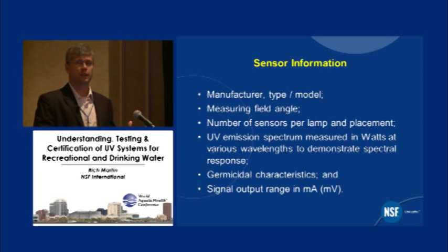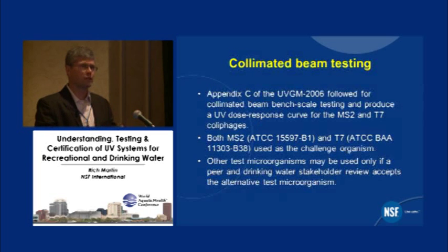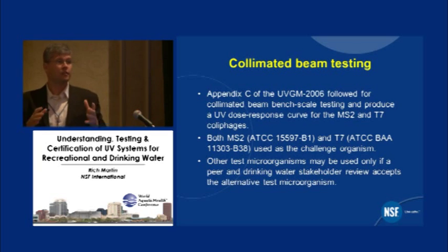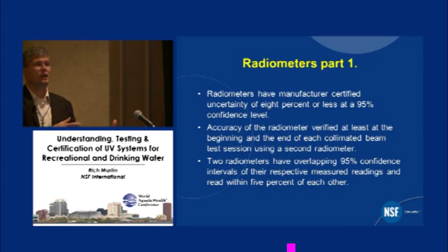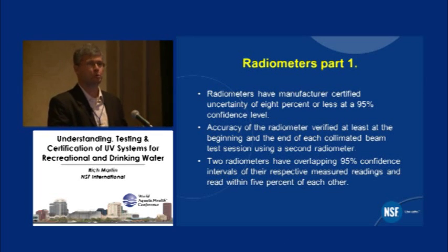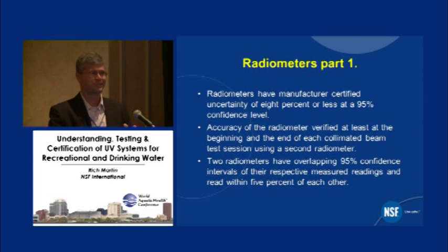So when we test and certify a chemical feeder, okay, there are all those health, safety, performance issues, but then you get into some quantitative examples of that. For chemical feeder X, how much does it really put out over unit time? Well, that's one of those critical numbers you need to know. So it's good to know it's certified, but what can it put out? Well, that helps me size the number of systems I either need to buy for that size of the pool based on how many users are in the pool, the volume of the pool, the circulation rates. So it's similar and different.